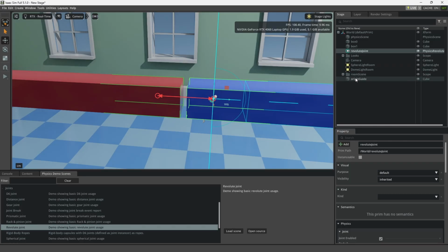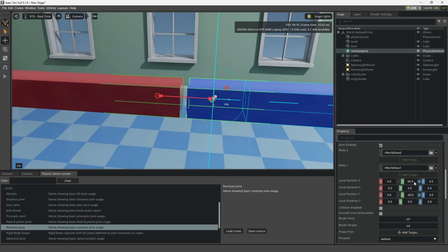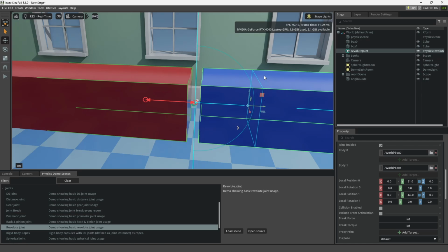That's what these will help you do. Because we're at 100 and not 120 now, if you change this to 51, and this one, you'll see that there's a silhouette of the beam here on the box 1 beam. If we change this one to -51, now you'll see that red went away, and what it did is it brought that silhouette of the beam together.